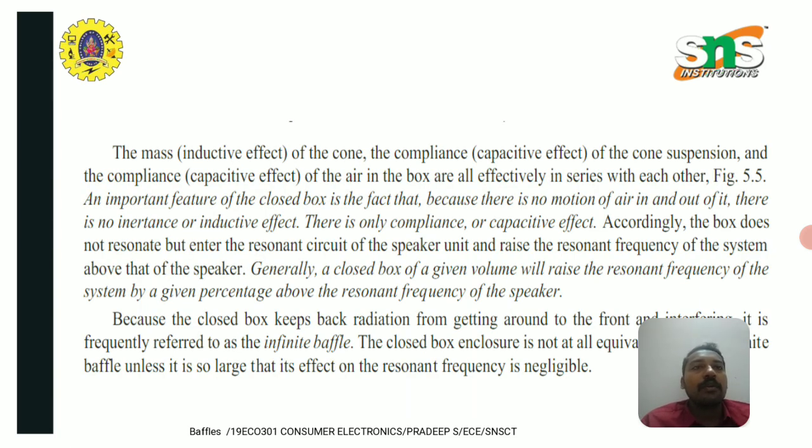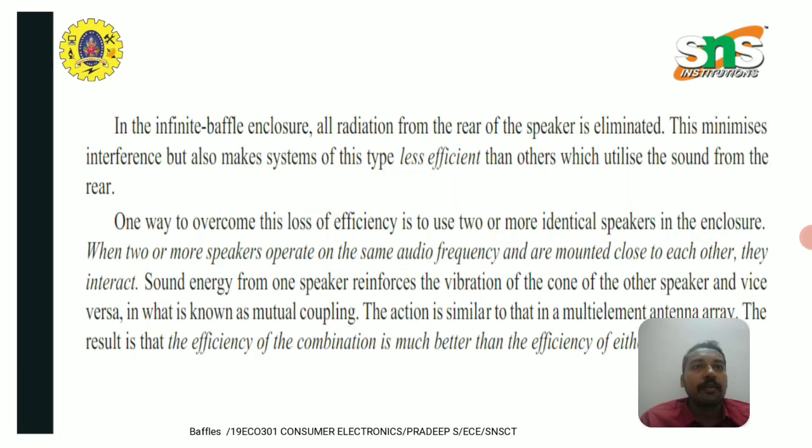The mass of the cone, the compliance of the cone suspension, and the compliance of the air in the box are all effectively in series with each other. An important feature of the closed box is the fact that because there is no motion of air in and out of it, there is no inertance or inductive effect. There is only compliance or capacitive effect. Generally, a closed box of a given volume will raise the resonant frequency of the system by a given percentage above the resonant frequency of the speaker.